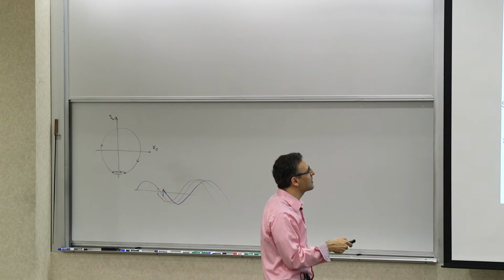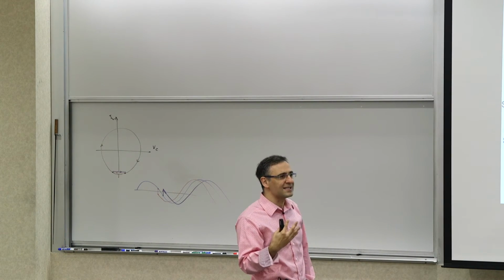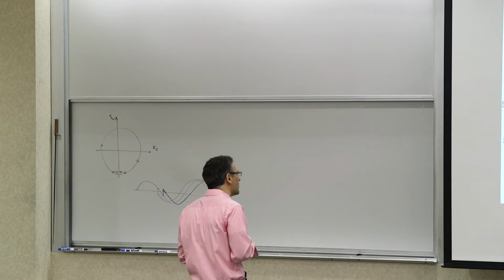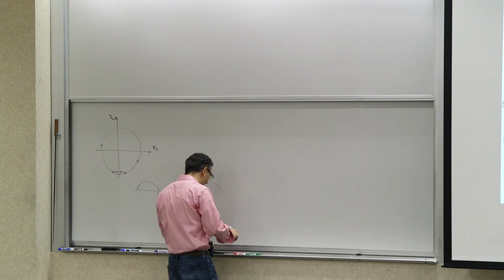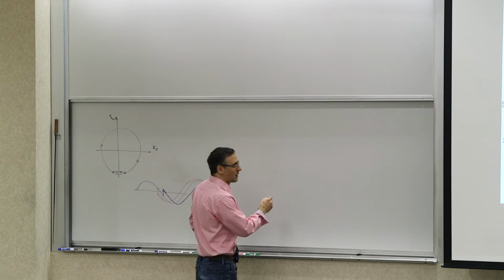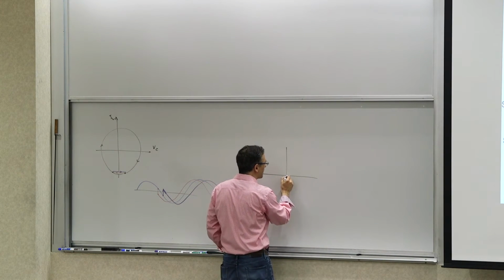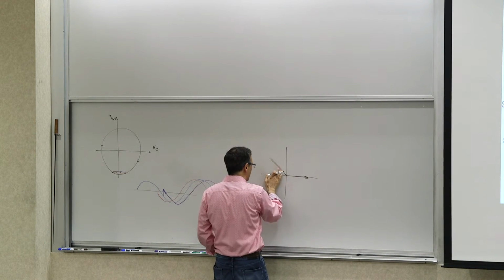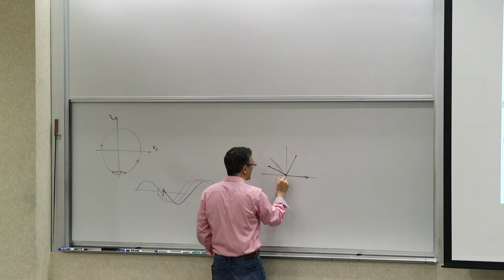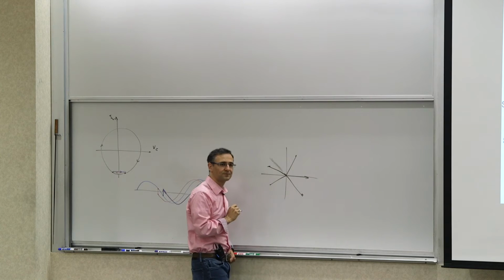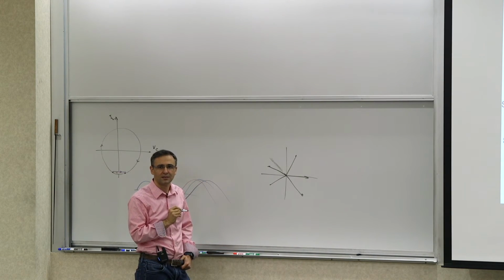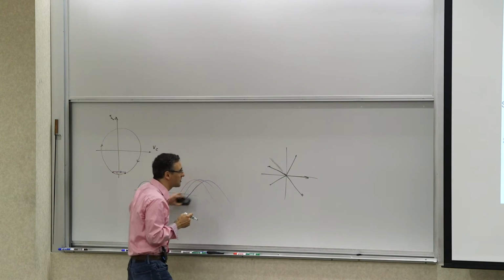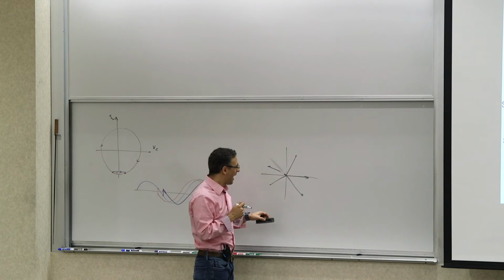Now, if you take that into account and write it as different phase shifts, so these ISFs are periodic waveforms, right? So let's think about what happens for a periodic waveform if you have 5 stages, and what happens for the fundamental. For the fundamental term, if you look at the fundamental of the first one, it would be here. The fundamental of the second one is here. Fundamental of third one is here. Fourth one is here, and fifth one is here, right? So what happens to the fundamental component in aggregate when you add all 5 of them? They all cancel each other out, right? So nothing is left. How about the second harmonic?